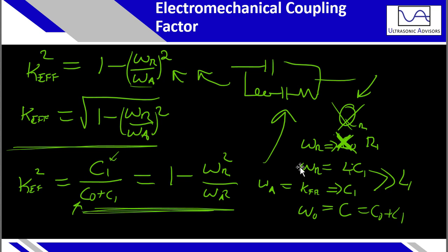So in that case, I would just measure all of the parameters such that you can calculate the coupling factor in many different ways. You don't need to rely on any certain method in case there are errors. You have those original parameters. The other thing to be aware of when you're doing your impedance analysis is what's called the existence of spurious harmonics. These are a little bit different from just other harmonics in your system that we'll speak about.